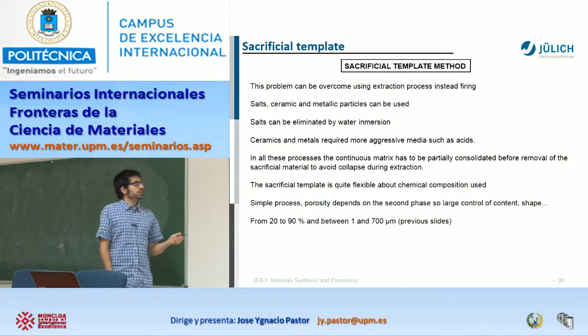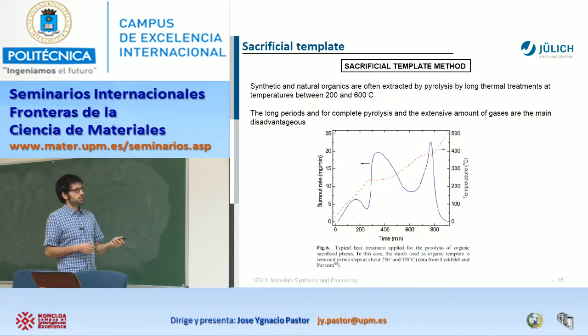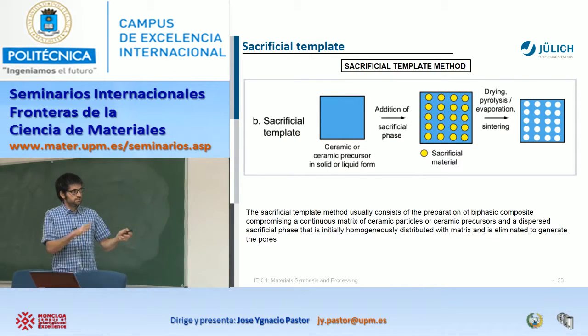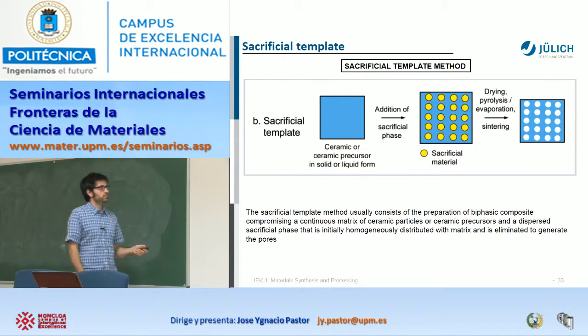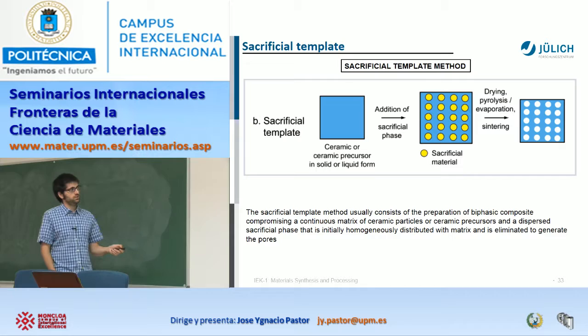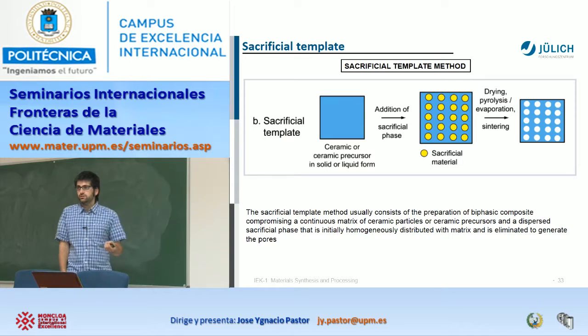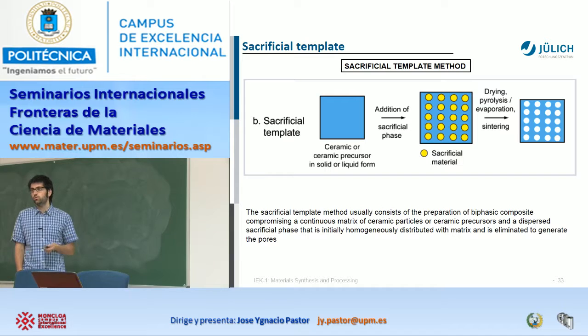But here is one solution. This problem can be overcome using another strategy, which is extraction. Until now we have talked about particles that you can burn out. But imagine that you add sodium chloride, and then you immerse it in water, and this sacrificial template will simply dissolve.